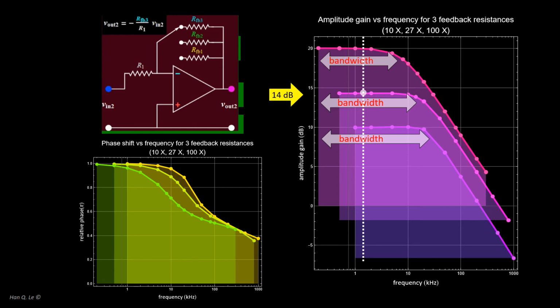However, suddenly the drone encounters something that has signal frequency in the high tens of kilohertz range around the dashed yellow line. The signal, as marked by the yellow dot, will be much lower in comparison, and the drone might not be able to detect the object. Hence, it matters to know the working frequency limit of the amplifier as obtained in step A5.